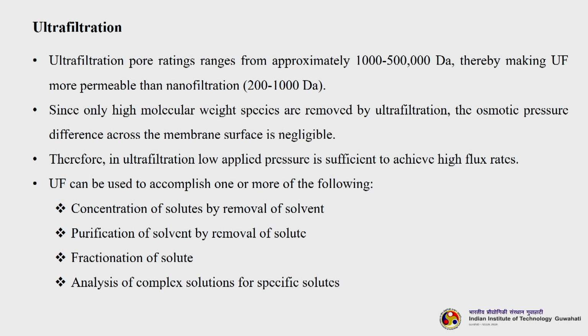So, ultrafiltration pore ratings range from approximately 1000 to 500,000 Dalton, thereby making ultrafiltration more permeable than nanofiltration. So, this is one of the most important things. Since only high molecular weight species are removed by ultrafiltration, the osmotic pressure difference across the membrane surface is negligible. So, we are not considering the osmotic pressure difference in ultrafiltration because only high molecular weight species are getting removed, not in the case of RO.